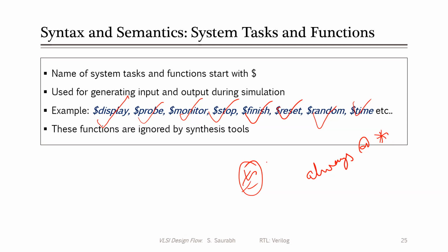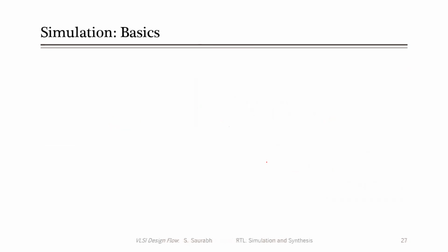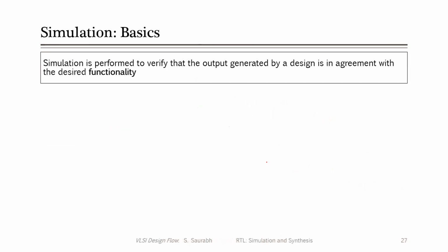So any other question? Okay, so let's move forward. Let's look into the RTL simulation. RTL simulation is performed to verify that the output generated by a design is in agreement with the desired functionality. This is basically the most important technique to do the functional verification for your circuit or your design.